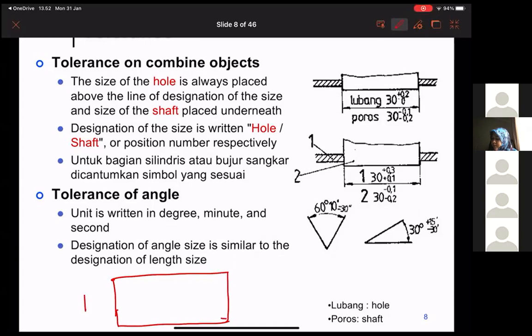It has a built-up diameter inside, made of alumina, or like a ceramic, to contain the heat in the area inside the furnace. This is called a rotary or horizontal furnace. Then I had to put some samples inside and do a reaction at about 1200 degrees Celsius for a few hours. My dissertation at that time was to produce magnesium metal.